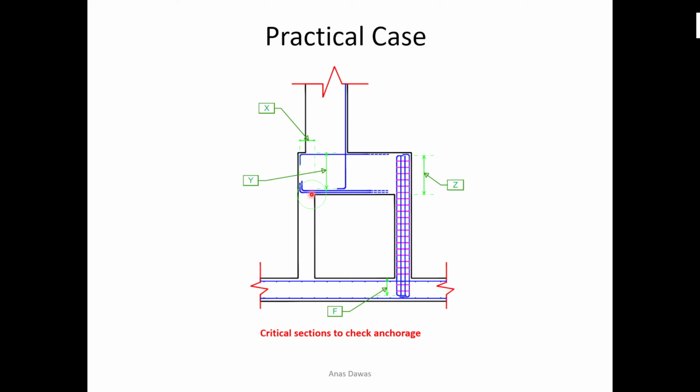By the way, for normal beams, for integrity reinforcement, the ACI code states that for some cases the bottom reinforcement also should be developed at the support, as a type of integrity to improve resistance to progressive collapse. Anyway, we will start with X here, top reinforcement anchorage requirements.